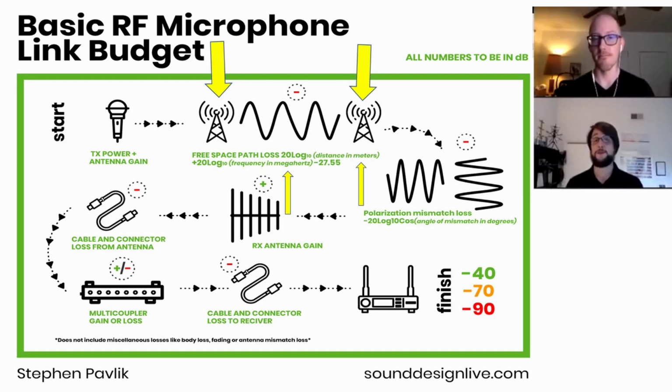I can tell you just through experience that changing the frequency in this formula doesn't change too much, but it's good to keep it consistent, or not consistent, but each one you input is fine. Or if you want to take the tuning band of your particular type of gear and pick a frequency right in the center and use that as a reference, like I said, it doesn't change too much. It's mainly the actual distance, but it's up to you how deep you want to get. I like to go dead on every time. I like to find the frequency I'm using, go exactly, just to get as close as possible. But got it. So this number here, the distance in meters, is going to make a much bigger change than the frequency in megahertz. Yes.